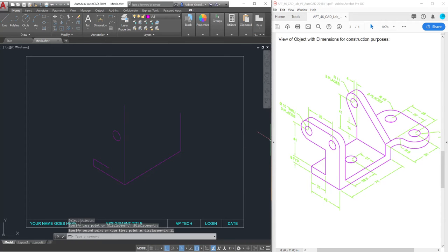So now I need this whole ellipse that you see here to create this portion of it. So I'll go ahead and go back to this one. You can also type in the command ellipse. And I'll pick the center point of this ellipse. Before I do that, though, I want to make certain I invoke the ISO circle option. So now I'll pick the center here, and now I can type in a radius of 11 and press enter. So now these are in the correct location.